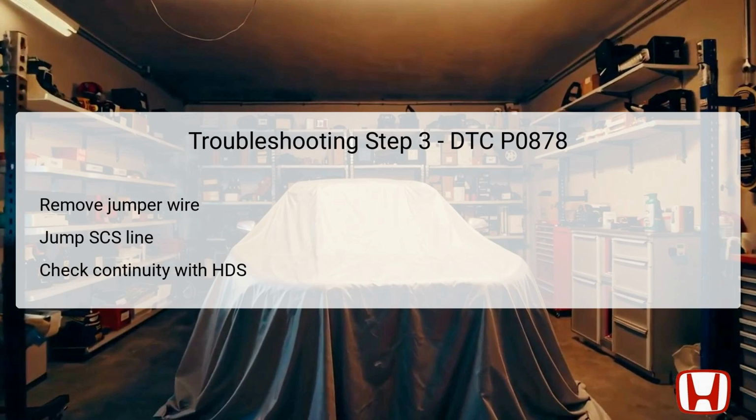Disconnect the PCM connector B and check for continuity between the designated test points 1 and 2. Test point 1 pertains to the transmission fluid pressure switch D connector, while test point 2 corresponds to the PCM connector. By ensuring there is no disconnection in this line, you can ascertain whether the wiring between the switch and the PCM is intact. If continuity is confirmed, it suggests the wiring is functional, leading to a potential PCM replacement scenario. Conversely, if not, focus on locating open circuits in the wiring.